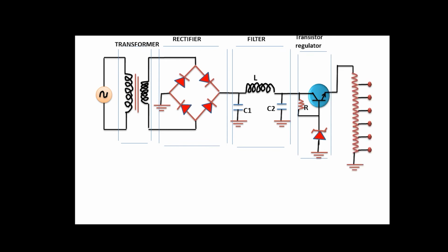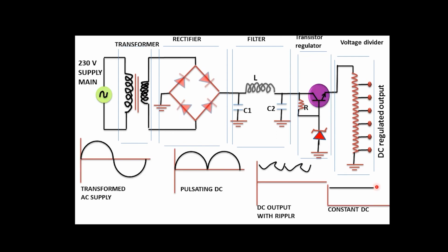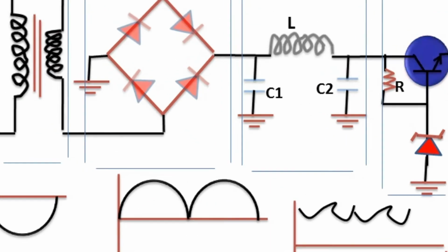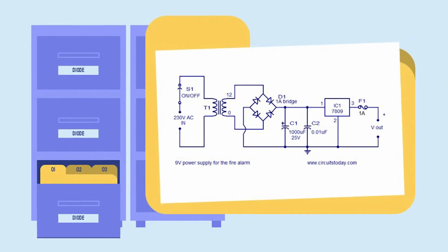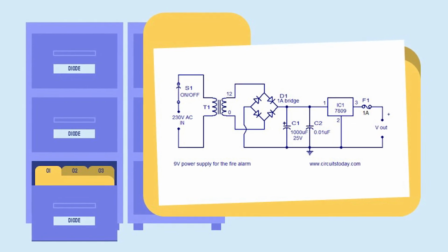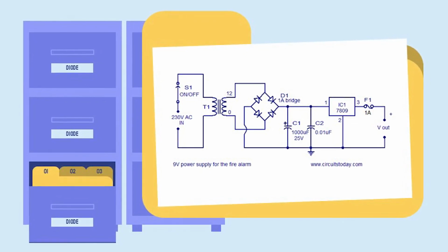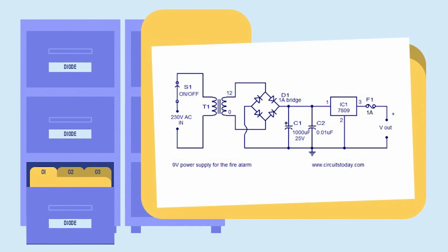Therefore, if AC is the type of power delivered to your house and DC is the type of power you need to charge your phone, you are going to need an AC-DC power supply in order to convert the AC voltage coming in from the power grid to the DC voltage needed to charge your mobile phone battery. The picture shows the circuit in a power supply, which includes that an AC to DC power supply is built using a transformer and a full-wave rectifier.